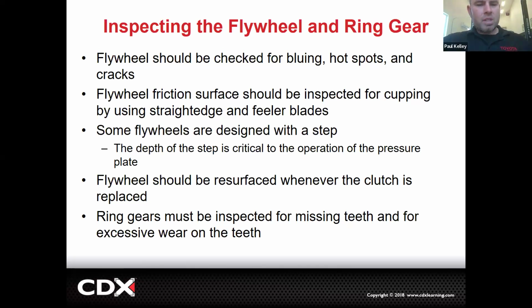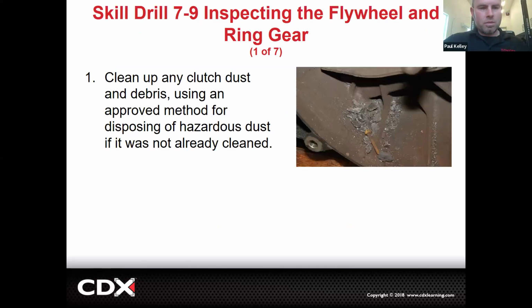If they're designed with a step, just remember that depth of the step is critical to the operation of the pressure plate. So that means if you inspect it and determine it can be resurfaced, you might want to do a measurement and make sure that the machine shop machines it to the same step. So if you're really sketched out, measure that step and find out how much it is. Then when you get it back, measure it, make sure the step is the same. Cool. But hopefully the machine shop's decent.